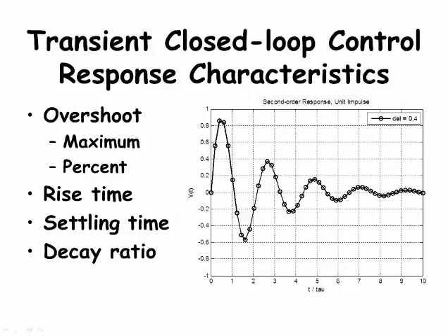In the previous video on second-order systems, we talked about several transient response characteristics that people use to assess the dynamic response of a closed-loop control system that may have only feedback control or might also include either cascade or feed-forward control too. Good control in Section 26 of the course packet will be defined as control in which the maximum overshoot is 25% or less and the decay ratio is about 0.25 or 1/4. You may in certain circumstances have other performance criteria.